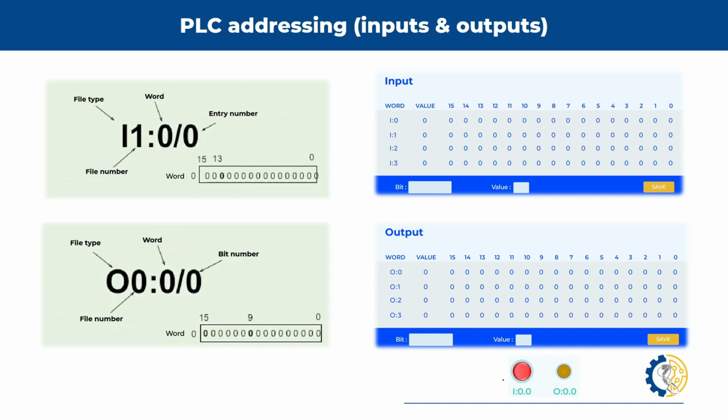So my nomenclature is E, and this means that I'm assigning an input, which in this case is a push button, which is an image for our simulator, semicolon, 0, which is module 0, point, and this is where I'm connecting something in my memory.